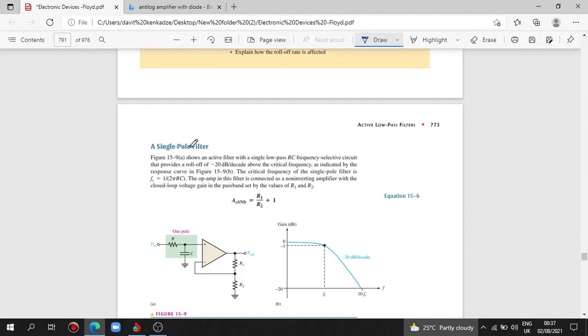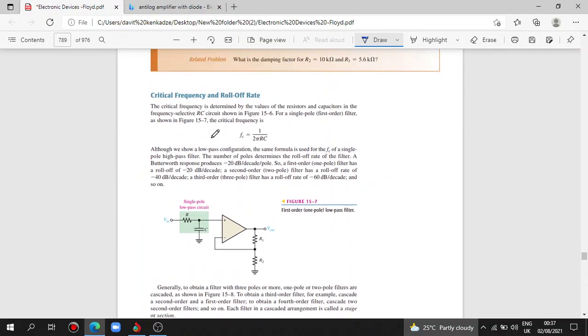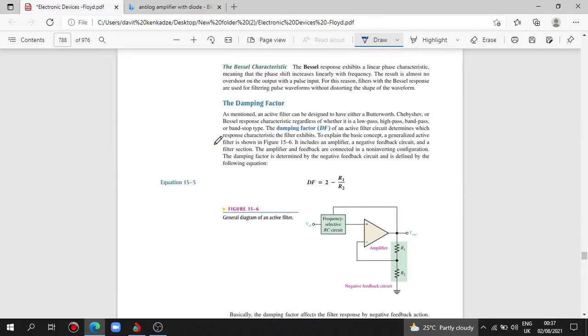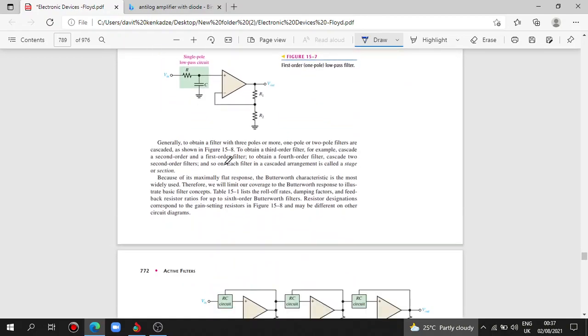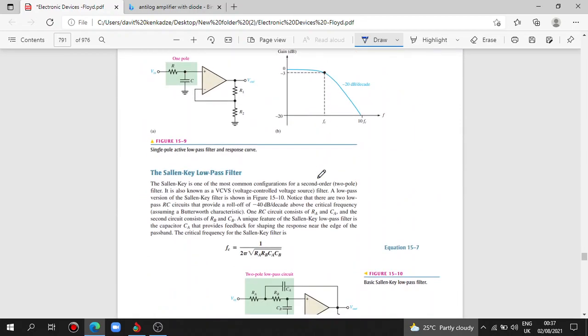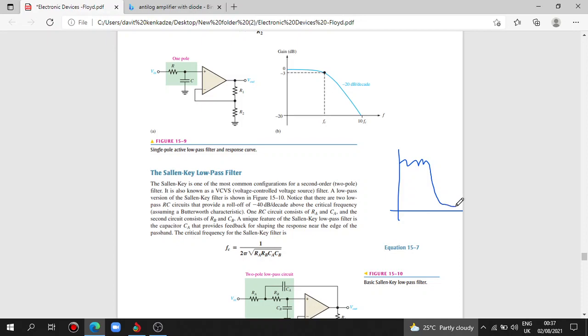Okay, about the ripple number, we have a Chebyshev filter, for example. It looks something like this. Here are the ripples, and then it drops. This is the passband. The roll-off transition from passband to stopband happens fast, but in the passband there are ripples.